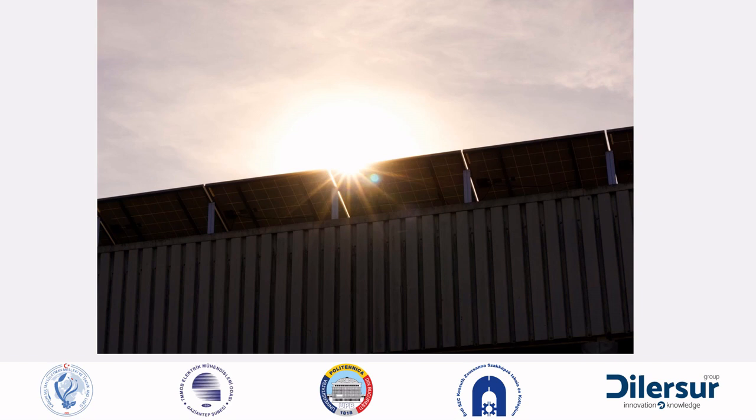One reason why solar panel systems are dangerous to work with or near is that they are very often installed on rooftops or on the sides of buildings. Consequently, some maintenance activities may imply working at heights, so falls are a major concern. In addition, the solar panels generate electricity all the time except in complete darkness, so anyone working in proximity to a solar panel must respect, understand, and take precautions when completing their tasks.